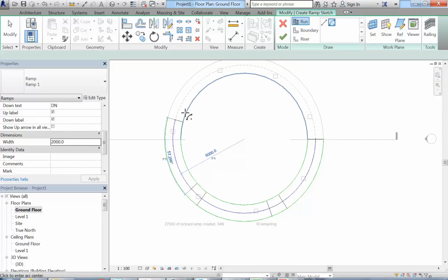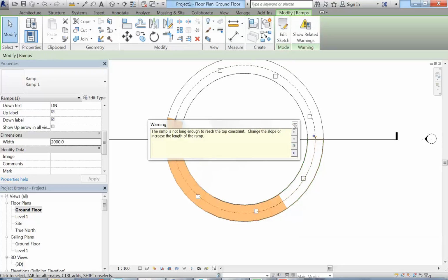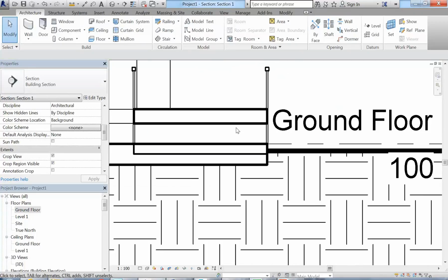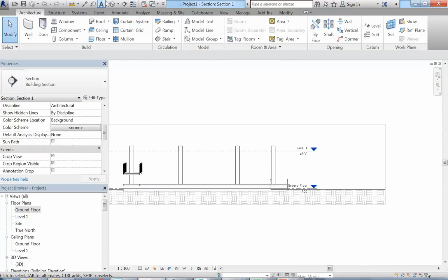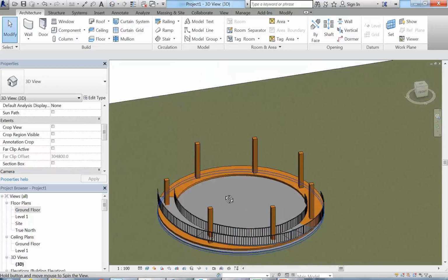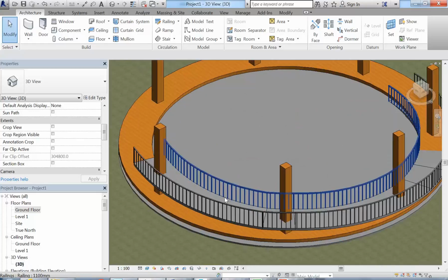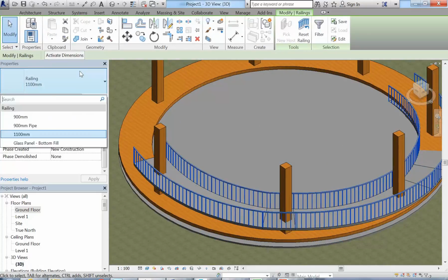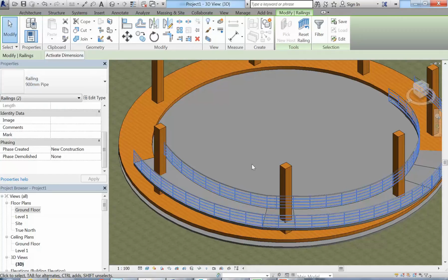Now you do have that option, you can go over the top, but it will make it more prone to errors, and so often it's better to break it up into smaller ramps. So here I've got the ramp, I'll show you in the 3D view, the ramp's working. And we'd fix the railing probably as well. It's actually nice that it gives you a railing automatically. You're going to need a railing probably, but it doesn't need to be that ugly one.